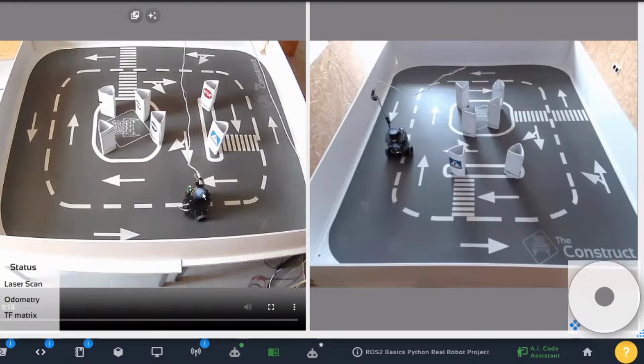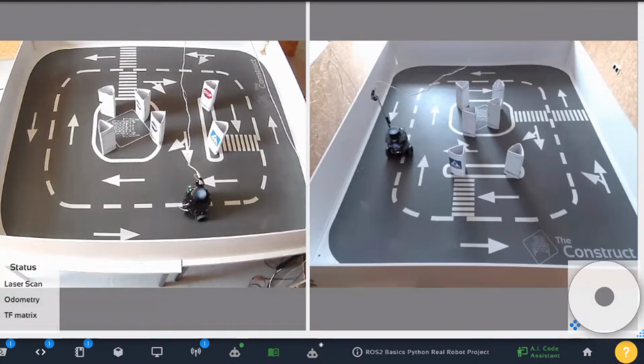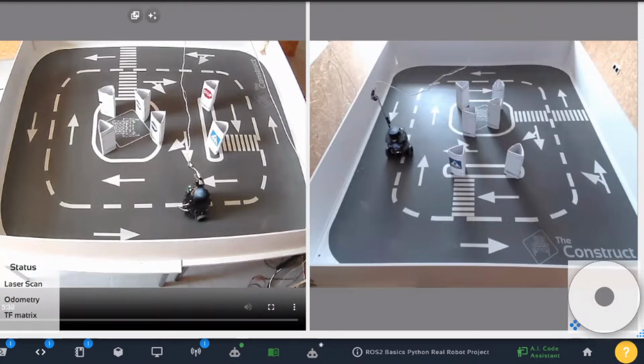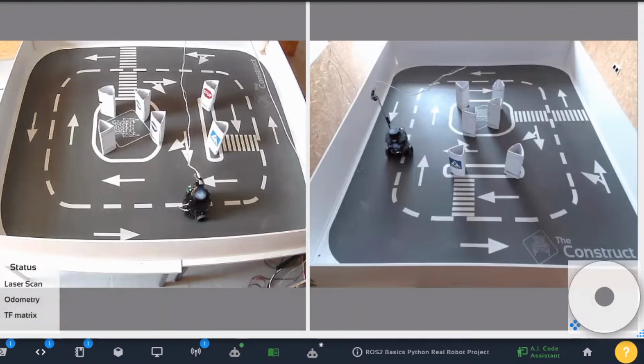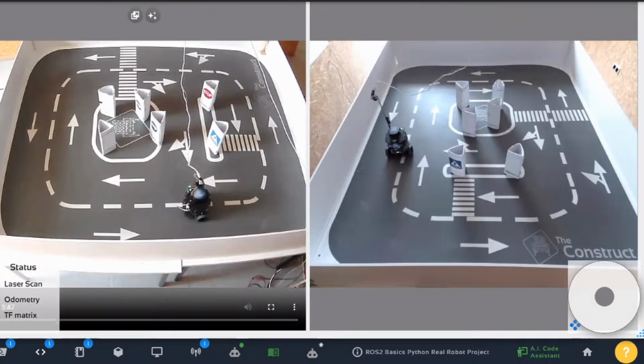First of all, it will have to locate the wall, get to the correct distance to the wall, then align itself, leaving the wall at the right, follow the wall, and complete a single lap. When it completes the lap, it should report the position points it has gone through. And I've made the robot stop just to check when exactly it arrives to the point. It may work or it may not. There is a little bit of error in the position of the robot. So depending on where you place it and the obstacles, it may not be completely capable of stopping exactly at the starting position, but it usually should do it close to that.